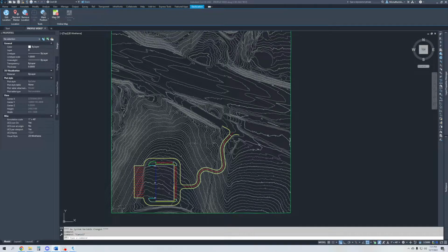So this one is going to be on surfaces, surface edits, and feature lines and feature line creation. So to start off, if you are working in the construction slash civil industry, you'll hear people mention surfaces. Surfaces are elevation data for your drawings. Generally, it comes from a surveyor. Sometimes you can get the information from your local county or jurisdiction, whoever may have that information. You can even get it from U.S. Geological Survey. They have some information that's made public.